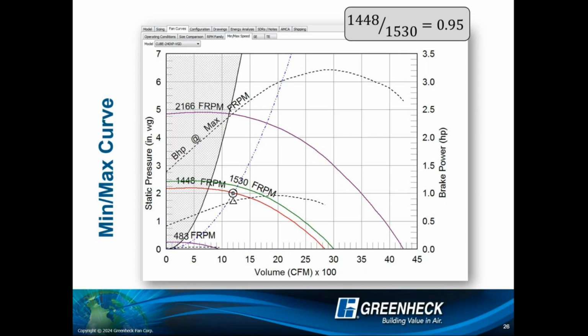So as an engineer, I'm going to play things a little tighter, right? I want the most cost-effective fan, with maybe a little less variability. Now, I start working in a hospital, or a project with multiple inlets and curves, and we're spanning floors. There's room upon room for inefficiencies to start sneaking in, extra elbows. Is 5% turn up a good idea there? For me, I start playing things a bit more conservative. And it's much easier for me, by the way, because I'm playing with your money, not mine, right? But I start playing more conservative.